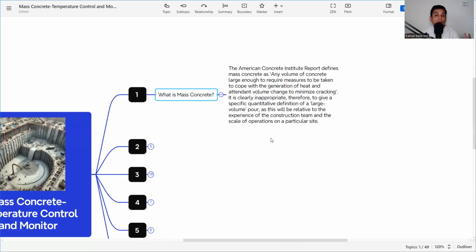And if the thickness of the raft, column, or pier is more, there is a tendency for a temperature gradient to be created. Then heat will transfer from the higher temperature to the lower temperature, and cracks will generate, and also shrinkage cracks due to the sudden change of volume. So we need to take care of the concrete in order to prevent cracks and the thermal gradient.